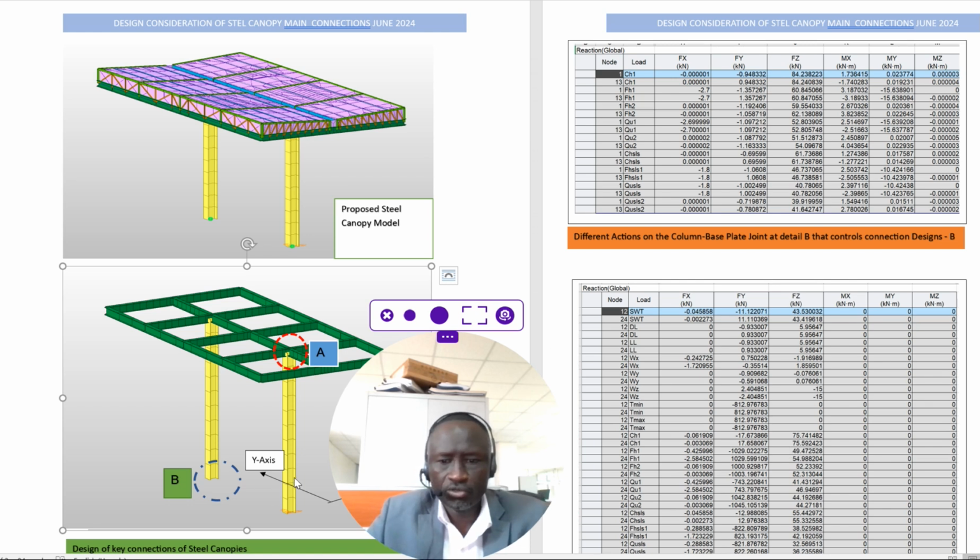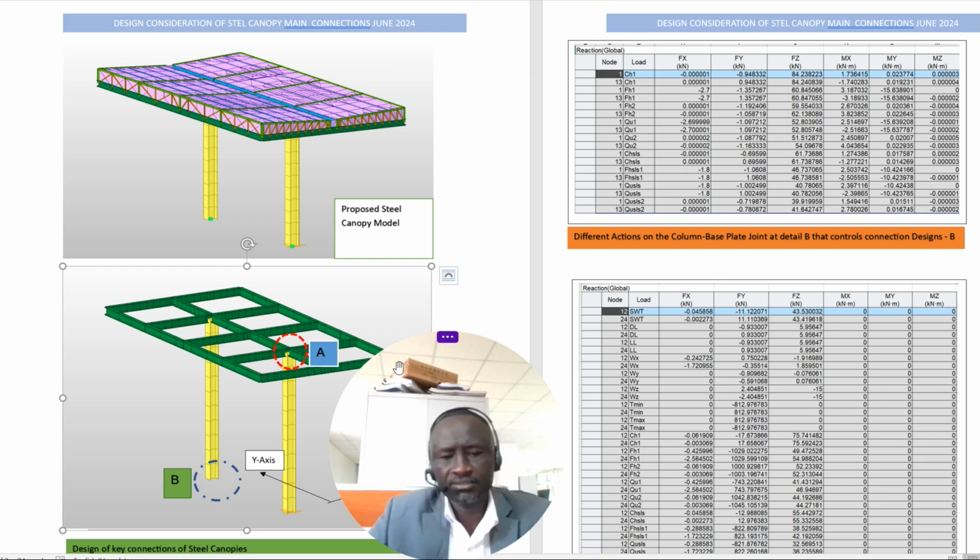If you want to take your vertical load, you do tributary area and then you get a vertical load and X. Sometimes even the Y loading you may not be able to generate in some of these components. So sometimes it is beneficial to use software to do some of this complicated analysis, so that you are able to get the exact loading, and then you use your code of practice and other literature and texts to help you design. If you look at McGinley, Structural Steel Design by McGinley has very good bolted connection and base plate design, which I think will be able to guide you properly here.